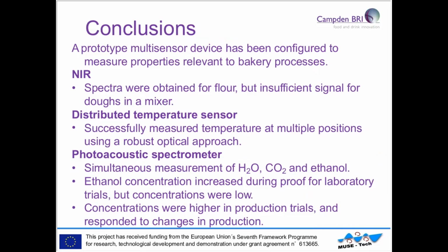But for measurements in the prover, we have demonstrated very nice measurements of temperature with an optical approach that doesn't have all the issues of cabling that you'd have with electrical methods. And we've also been able to measure the gases that are present in a prover. In a laboratory, we were struggling for sensitivity, but when we use a full-scale production trial, it works much better, and we can see some changes in response to variations in production.